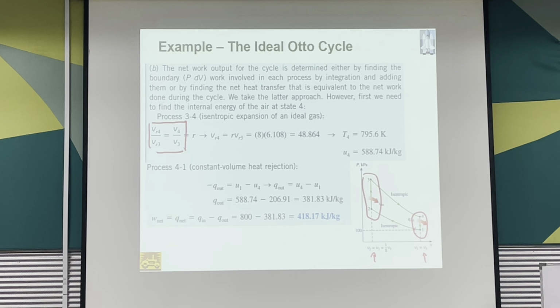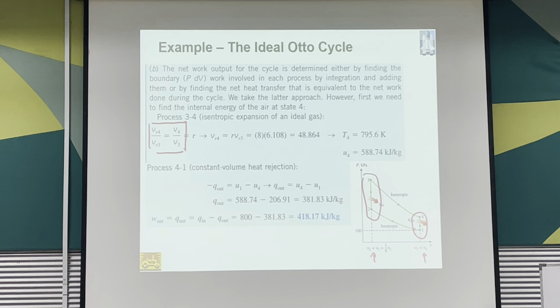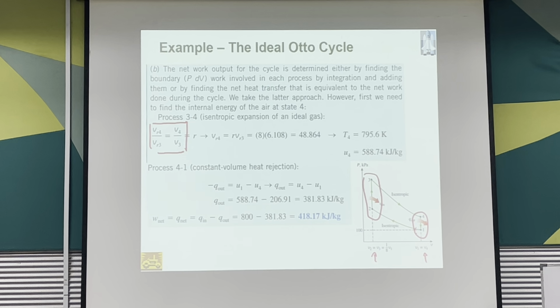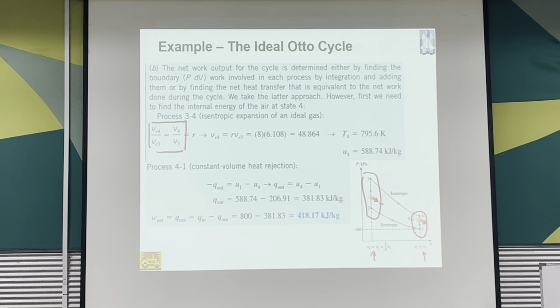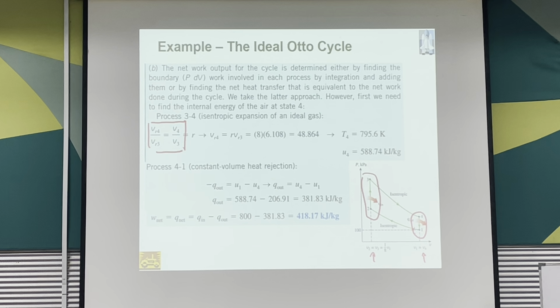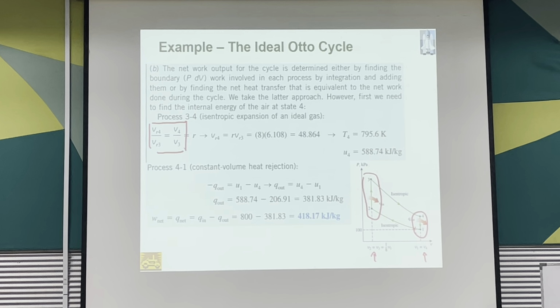Now, for me, usually when I solve a cycle type of question, even if the question doesn't ask, I will always sketch out either the PV or TS diagram first, and I will ask you to do so also. This diagram serves as a guide on how you can solve the question, because sometimes you don't remember when the volume is the same. When you look at the graph, you can see that it is actually there.